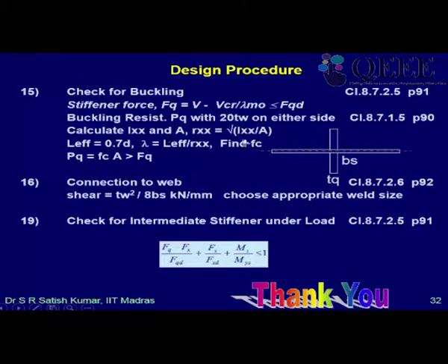We are providing such that we assume some depth of the width of the stiffener and thickness of the stiffener. We may even provide on both sides. And then this plus shape, imagine this is a cross section for a column. This has to be now checked for the applied load, if it's a point load, or if it's a reaction, the reaction at the support.